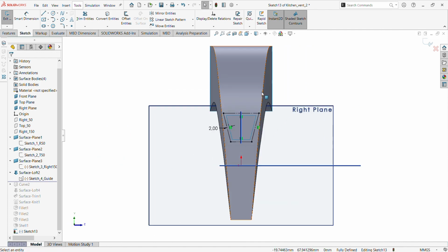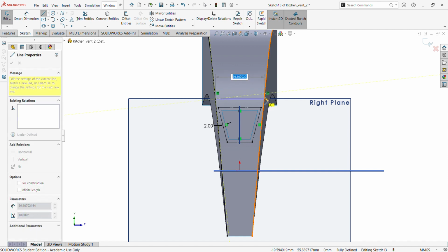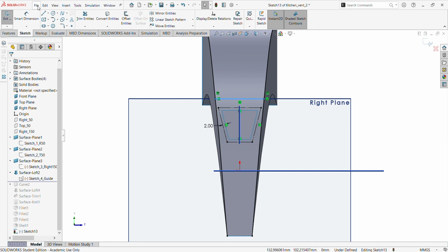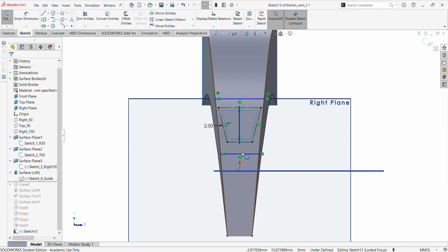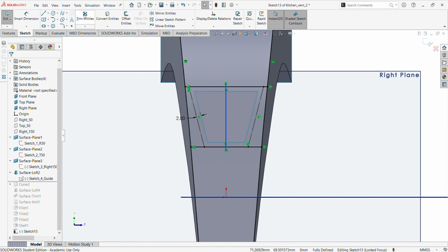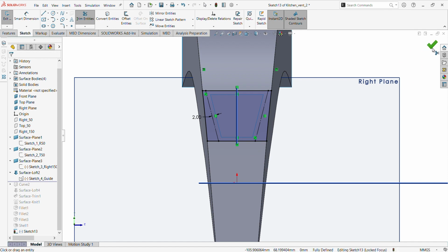So, okay, we offset this surface so the loft will lap exactly on this surface. Convert entities. Okay, so we can draw the sketch. So there, draw the second sketch. You can still add a relationship if it's not snapping properly. It should be collinear. We should add a collinear. Make this both collinear, and then we should now do a bit of cutting here. Cut that surface. Cut those lines. So we got what we want. Yeah, all right. And then yes, exactly. We want it to lap at the appropriate point. So we approve the sketch.